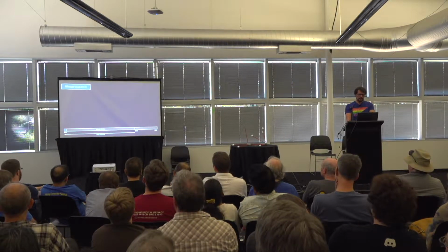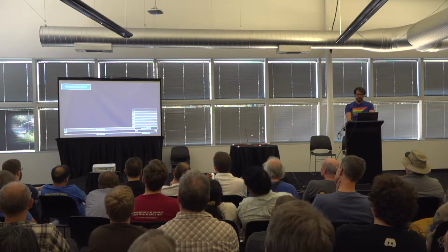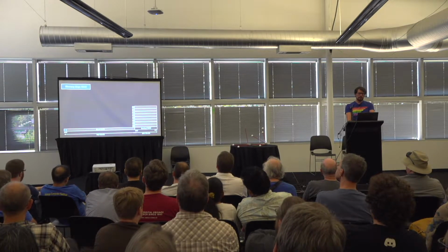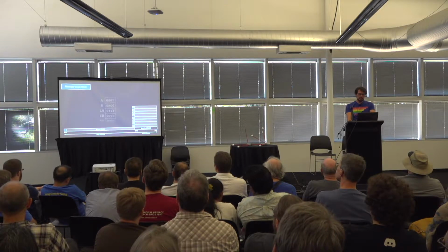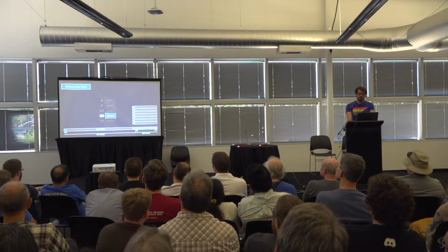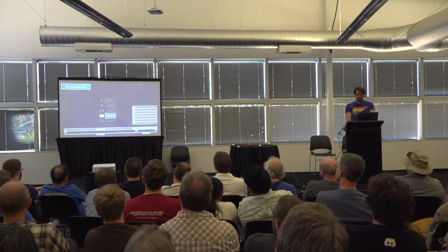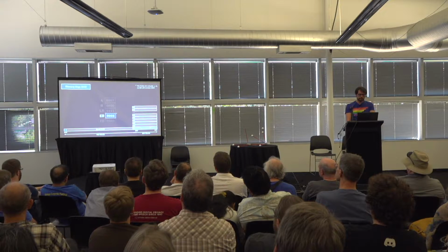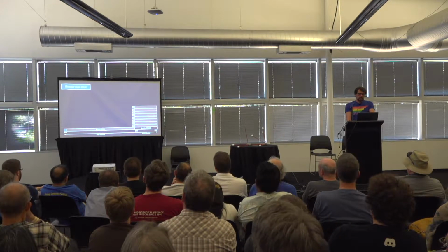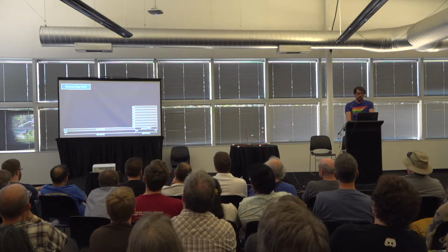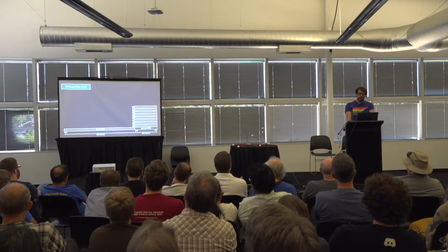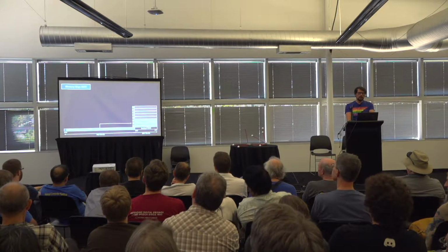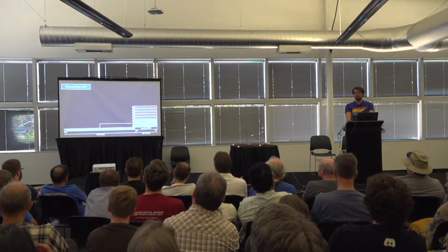Let's look at the RAM area. The uppermost quarter is banked. This quarter is a window through which one of 8 different banks can be accessed, each 256 words in size. The erasable bank register, EB, points to one of these banks. If EB is 0, bank 0 is visible in the banked area. If EB is 5, bank 5 is visible. Addresses in the fixed area always represent the same RAM cells, but these are not additional cells, but the same as banks 0 and 1. This means that there is a total of 8 times 256 words of RAM, 2 kilowords.